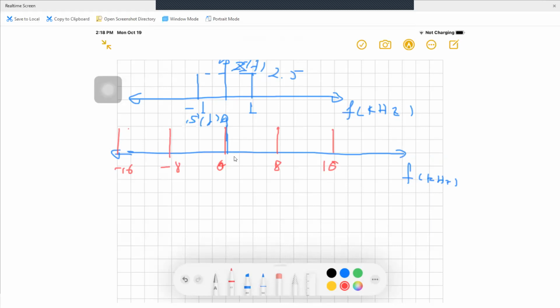In the previous lecture, when we derived the formula, we said that the f-axis for the S of f will be 0, fs, 2 fs, 3 fs, 4 fs, and so on. So here in this example, we have 0, fs, which is 8 kilo, 2 fs, 16 kilo. 3 fs will be 24 kilo, and so on. No more, no less. Now, what will be the next step?